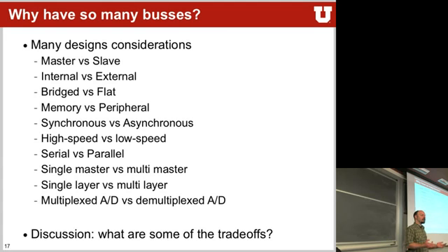Now, if you want to push that out of the chip, you need 64 I/O lines hooking up to it. And that's not all, especially not in the AHB case. The AHB, I think, has about 128 different lines that go back and forth to make stuff really fast. But as soon as you go external, you want to reduce the number of pins that you have. Make sense? So that's some of the big trade-offs that you have.